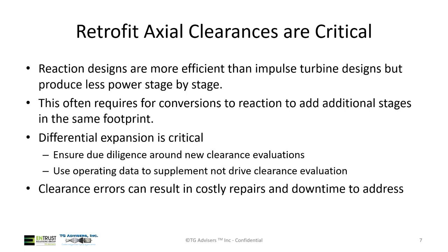Make sure that due diligence is done during design reviews for clearance evaluations, and make sure we're using operating data to supplement and not drive clearance evaluations. The important thing to remember here too is clearance errors. If you have a clearance error on a new retrofit unit, that can result in costly repairs and downtime to address. Those can be pretty costly repairs and damage.